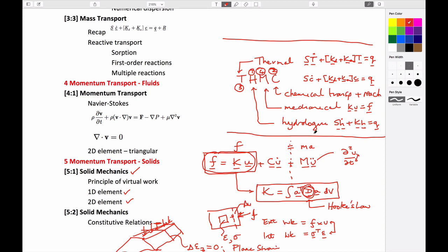We've talked about a variety of different expressions which on their own are completely independent. We could solve the heat flow problem just by solving a mesh with appropriate boundary conditions and with temperatures applied, and look at the propagation of temperatures within that system, and it wouldn't have any influence on anything else. It wouldn't change stresses at all. We could look in the same system at the mechanical behavior, and if the information about the thermal stresses was not sent or passed to the mechanical expression, then there would be no net influence.